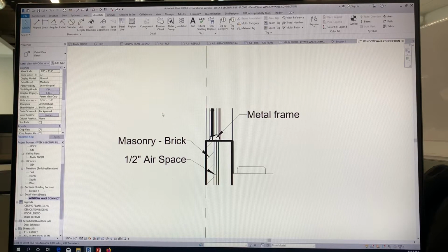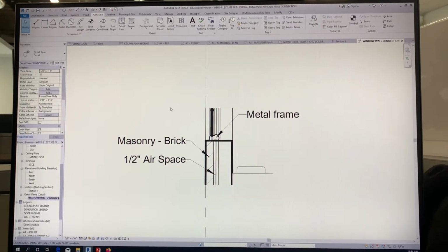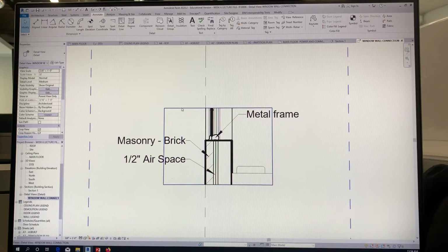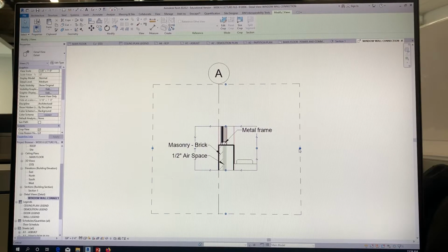It works, but when I try to do a material tag on the wall below, it seems not visible. So remember, if you're losing some of your elements, it's because it's too far from the drawing. Your crop region is probably cutting it off. Turn on your crop region, select it, and it's this crop region that controls text.